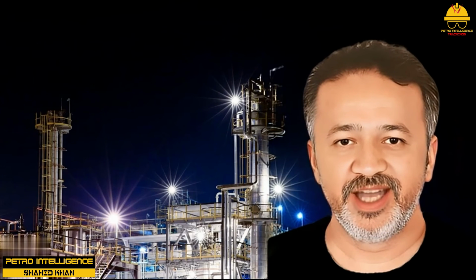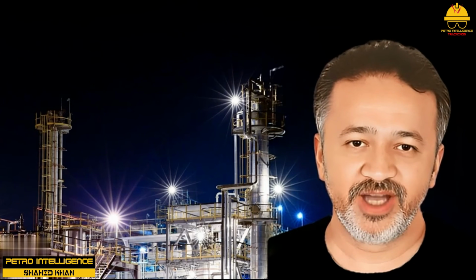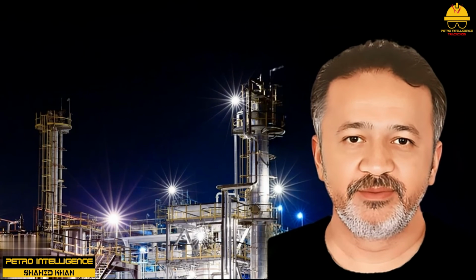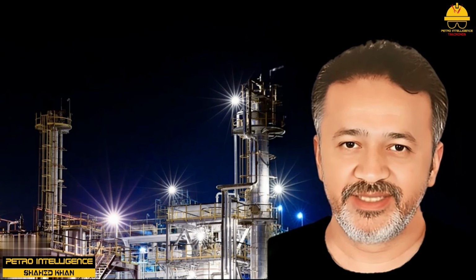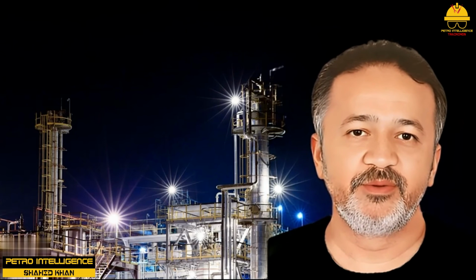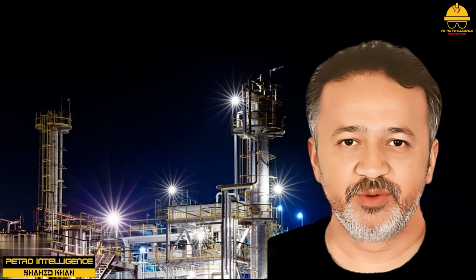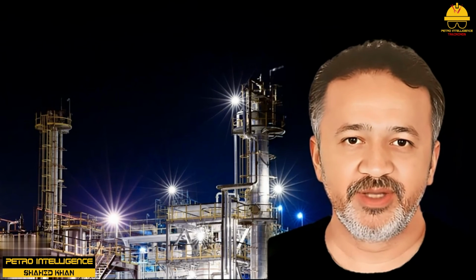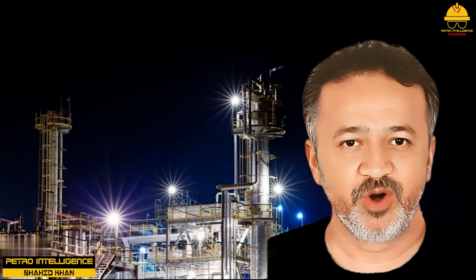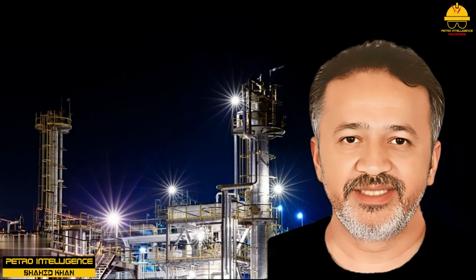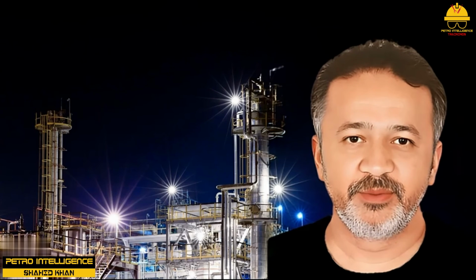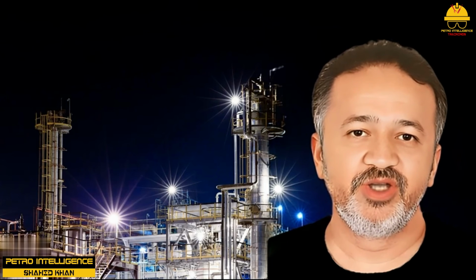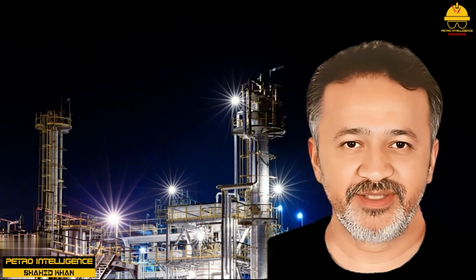Most operating personnel, if allowed to, would have a great array of instrumentation at their disposal to control and monitor a reaction system. On the other hand, many design engineers would like to place a minimum of elaborate instrumentation into a unit to decrease the plant investment. Somewhere in between, the unit obtains a sufficient number of instruments to operate the reactor in an efficient and safe manner. Instruments must be installed to detect and control reaction conditions such as temperature, pressure, feed composition, and flow rates.